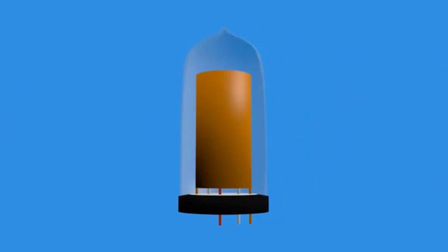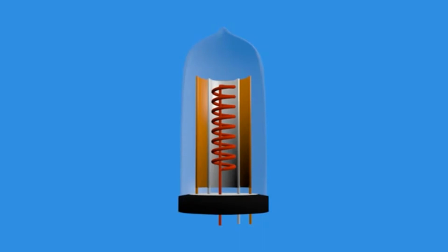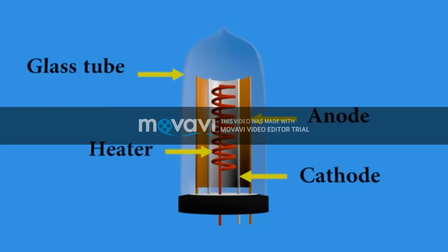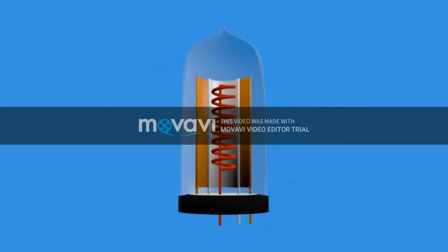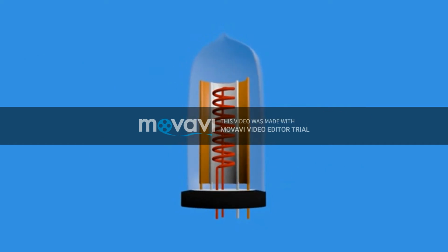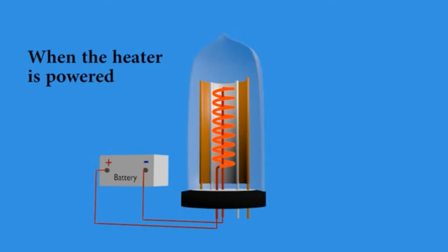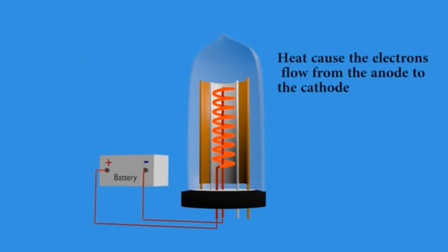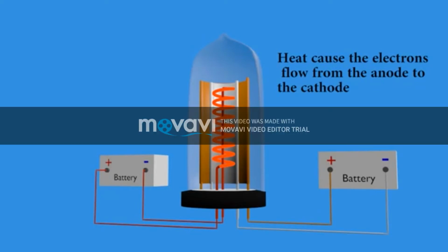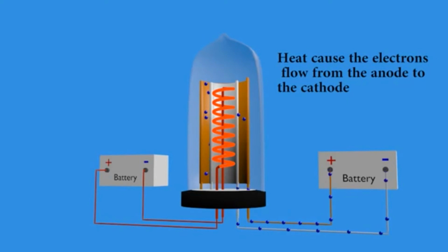The first application of this phenomenon was thermionic bulbs, also called vacuum tubes, and were invented by John Ambrose Fleming, an English physicist, in 1904, based on the models that Thomas Edison patented in 1883. The vacuum tube contains a filament called the cathode, surrounded by a plate, the anode, both sealed in an evacuated glass envelope. When hot, the emission occurs and there is a current flow to the anode if it has a positive potential. The current goes only in this direction because the plate or anode is not hot and doesn't emit electrons, being useful for rectification, for example, of an alternating current to a pulsating direct current.